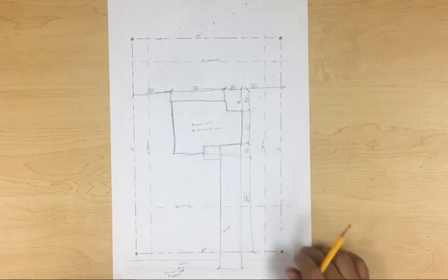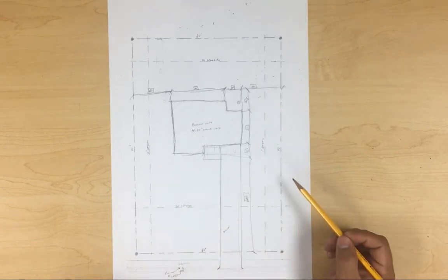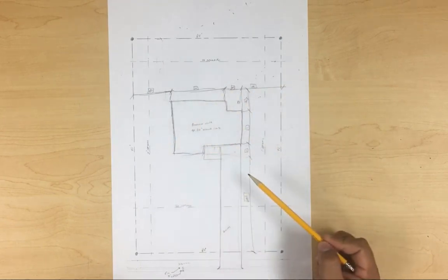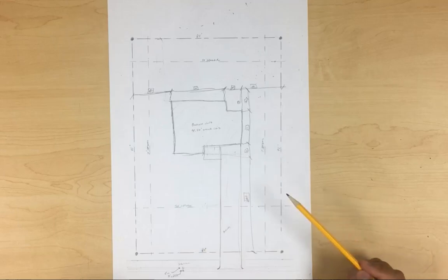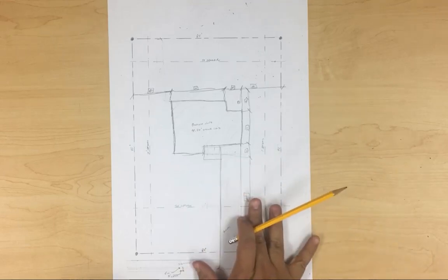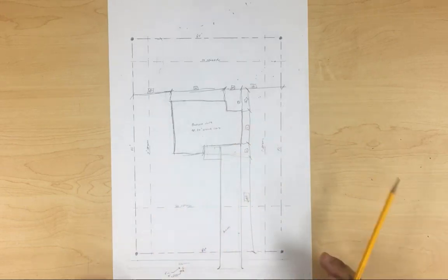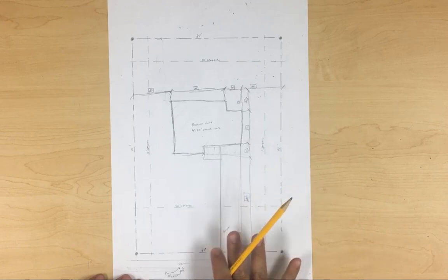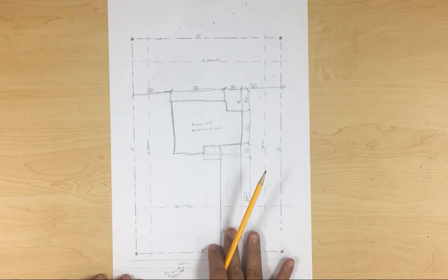Okay, so let's go ahead and draw this. Again, 1/8 scale. You're gonna have to redraw with the sizes that I gave you, which is 64 by 95 on the property, and do that as a property line. Then your setbacks with hidden lines. Put your structure wherever it's gonna be at, dimension it, and I'll add the information. I don't want to see a sketch, because I don't want to see just a bunch of lines. Do it with a scale, do it with straight lines, and then scan this and submit it on the assignment for chapter 2, which is site plans.